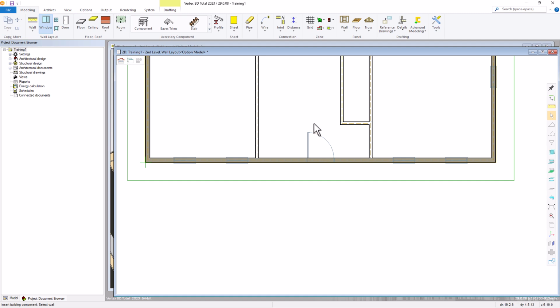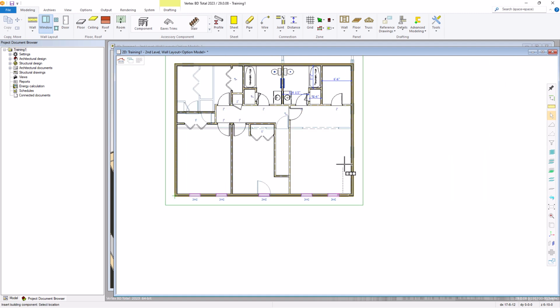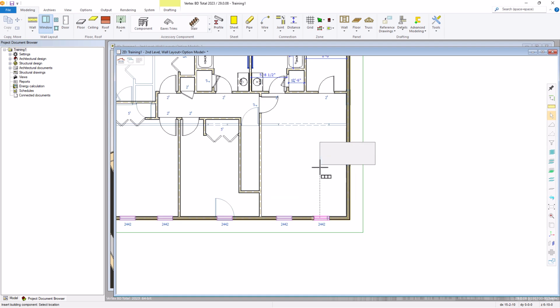and the front door. So we'll select this wall. We'll just need to go in and find the midpoint of each of these windows. And we'll find the midpoint of the door. We're going to add another one along the vertical wall to the right. So we'll right click, select wall, find the midpoint of that window there.